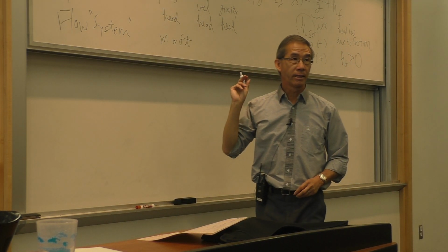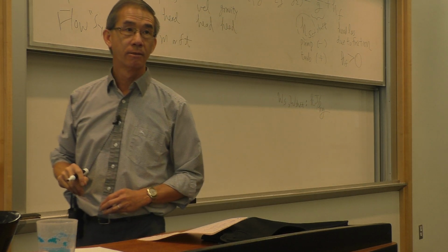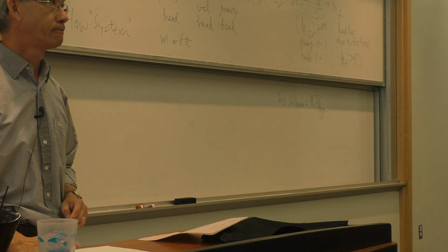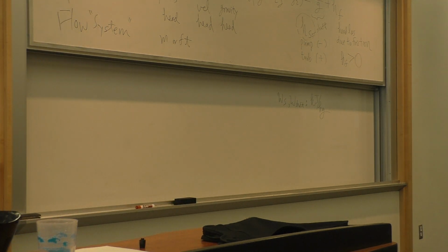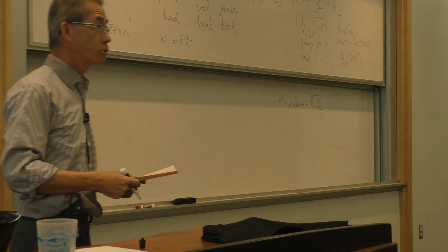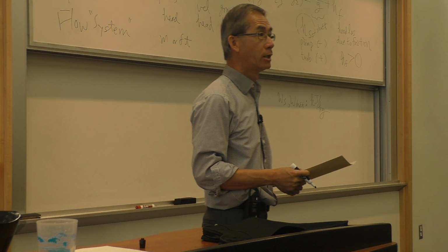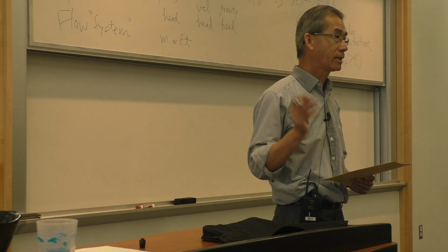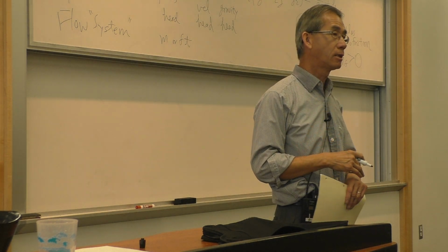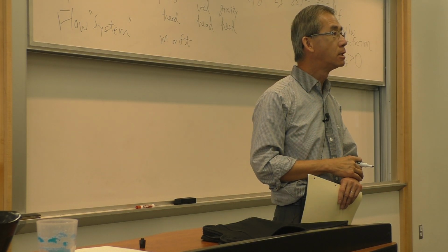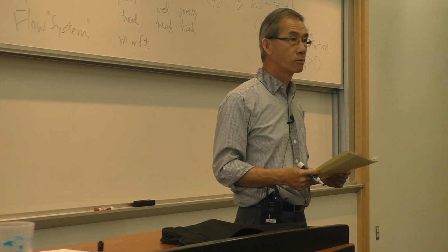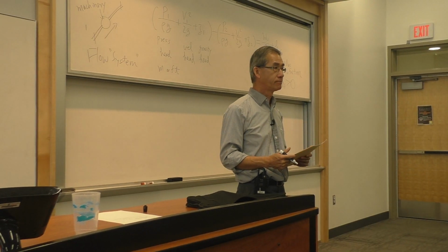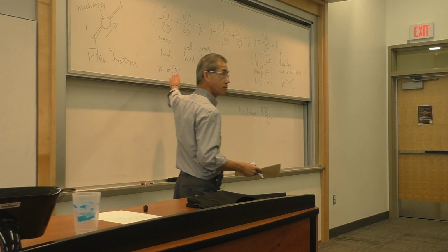And armed with the fact that H sub F, due to friction, is always positive, you can now make an attempt, using the energy equation from point A to point B, to figure out which direction the flow will go. It's not obvious. You can't guess. If you do, half will say up, the other half will say down. But using the energy equation, you will know conclusively which way it will go. Do you see that? Do you understand how to use this equation?